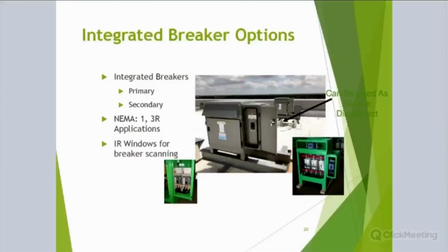You save equipment, you save footprint, you save cost of an additional transformer, and you save those additional losses because now we can drive the load up on a transformer more so. Instead of being 10-15%, if I have two panel boards on it, I should be in the 20 to 30% load. Well, that's right at your sweet spot of the design of the transformer. So therefore my losses are less. That's a very advantageous way of saving equipment and capital cost on a project, is providing a larger single transformer feeding multiple loads.